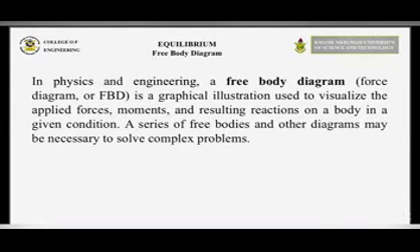The body in question may consist of multiple internal members. So the free body diagram should depict a body or connected bodies with the applied forces and moments and reactions which act on the body. Please note that in some complex problems, you need several or a series of free bodies and other diagrams to be able to solve such problems.